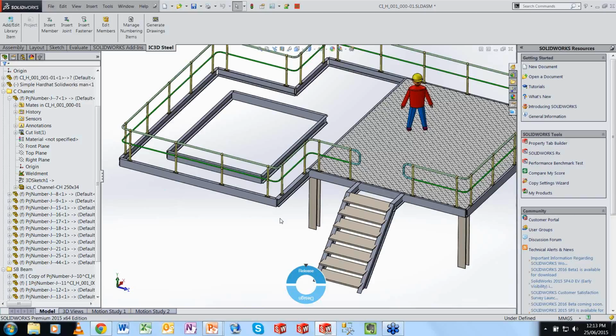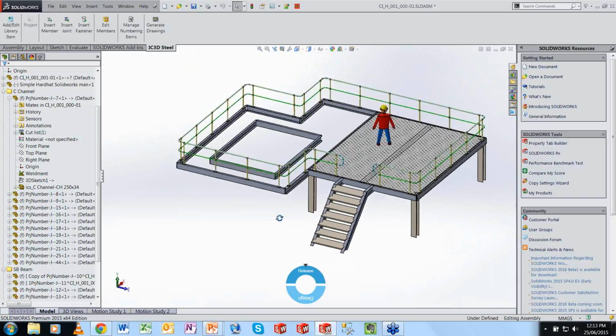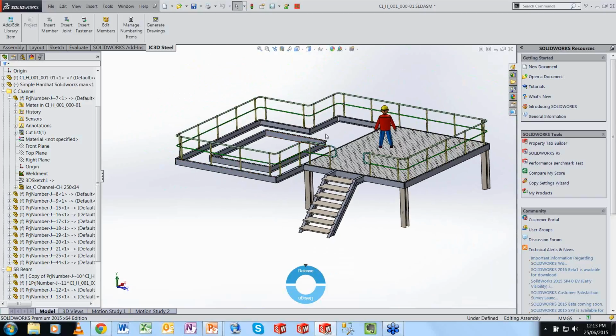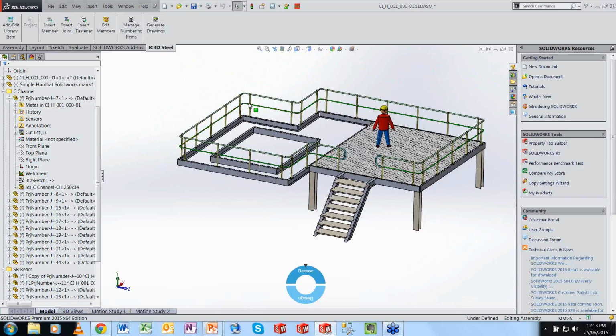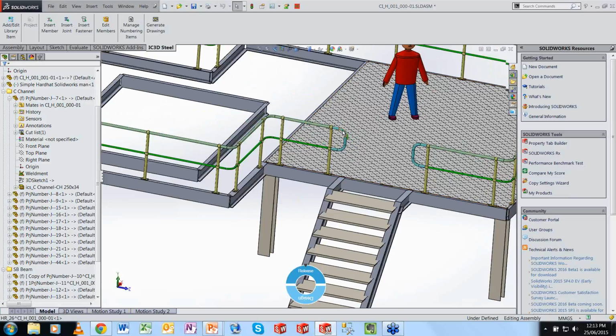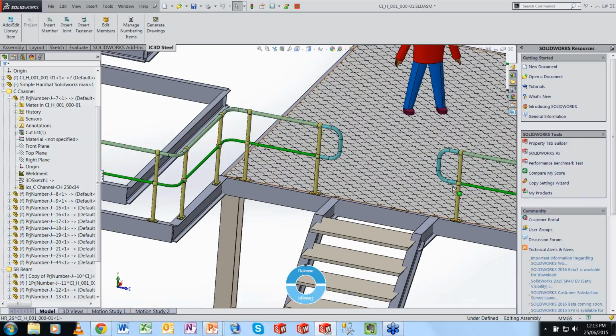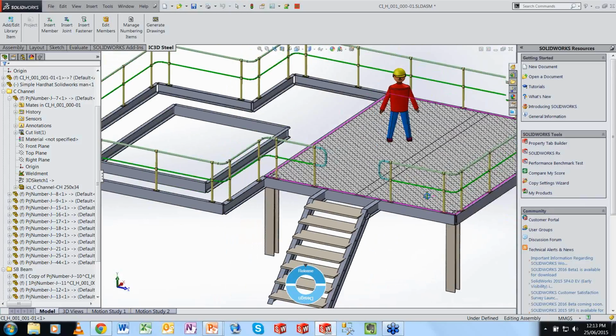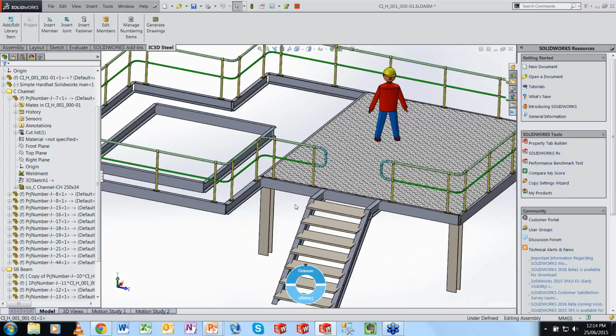And you can see that the handrails are created there. So you can see it goes right around the platform, adds bends at every corner, and as I mentioned, it accounts for the breaks that we've got. In this case, we needed an opening here, so it caps the ends of the handrails there as well. So it's quite neat in the way that it does that.